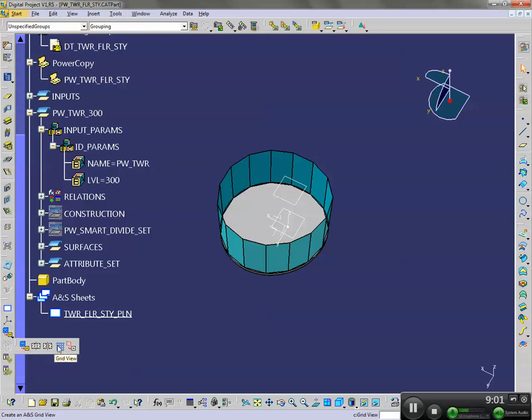There's a grid view, which produces architectural grids or levels. There's a section cut view, which shows just the elements that are intersecting with a plane. There's a section projection view, or a section view, and that's a section and then showing what's beyond. And then there's a front view, which is no section cuts. It's basically showing anything visible on a screen projected onto a plane.